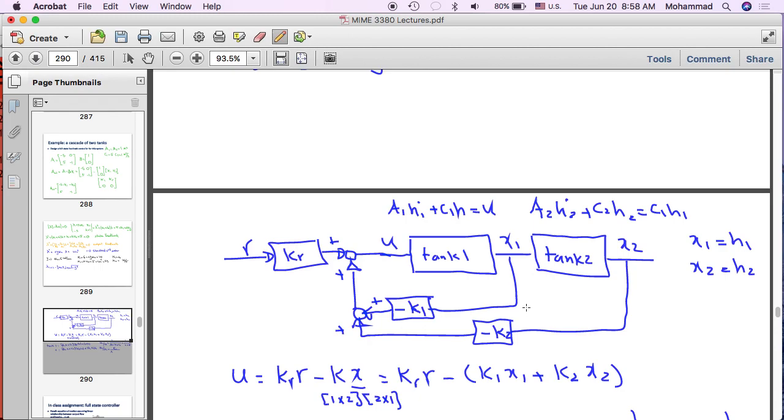This is the fastest response possible when you have damping ratio exactly equal to 1. Actually, I shouldn't say it's the fastest, because the two poles are now located at -5 and -5. If you move them both to -10, for example, you can make the system faster. You maintain the same damping ratio, but change the natural frequency to 10.